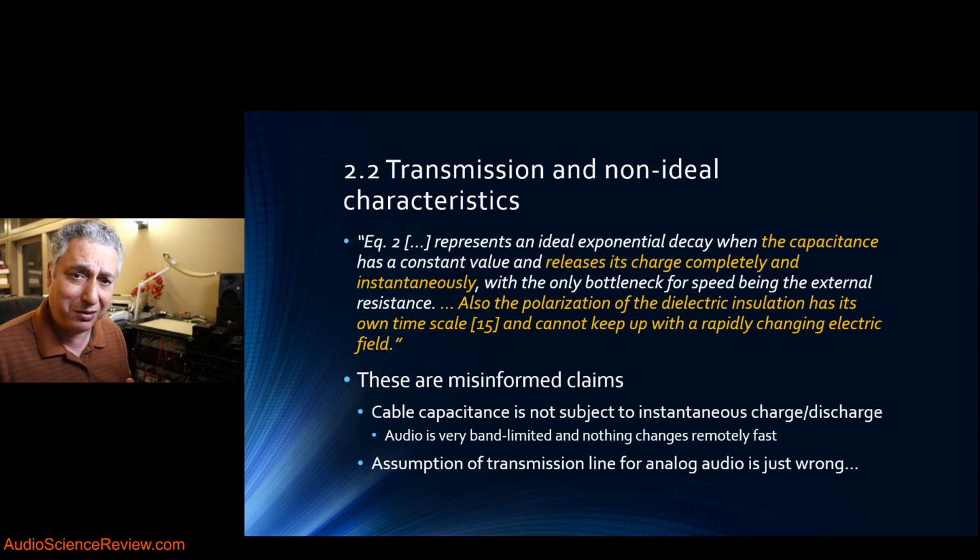Audio signals are extremely slow in the world of frequencies. We can go to many gigahertz and higher, and we're talking 20 kilohertz, the maximum we can hear. And so nothing is changing fast in the audio world. To say that the capacitance of the cable is instantly changing, and therefore we should go measure those instant effects, is just totally wrong. Nothing in your audio system would work if this assumption is true, because we have much larger capacitors inside your amplifiers and everything else. If those are instantly charging and discharging, well, then hell breaks loose. Nothing would ever work in electronics if that was the case. So the whole concept is ridiculous.